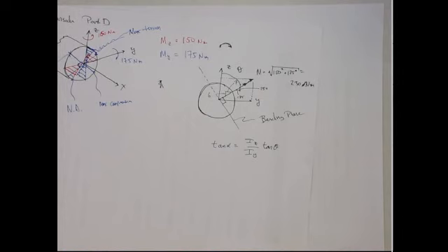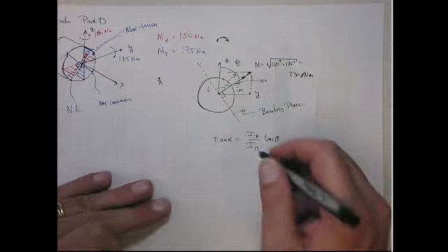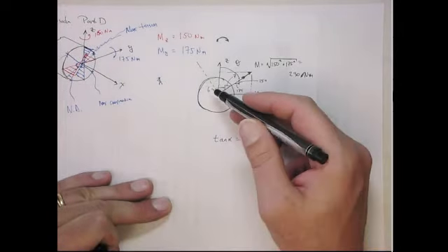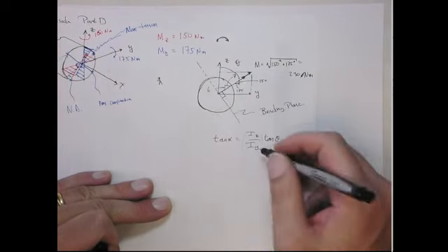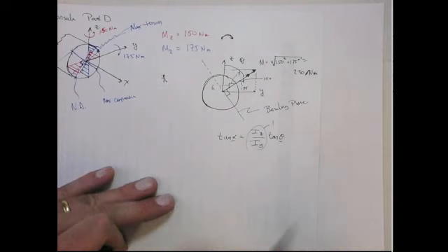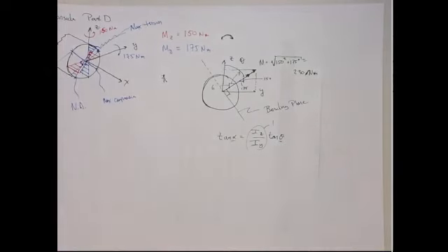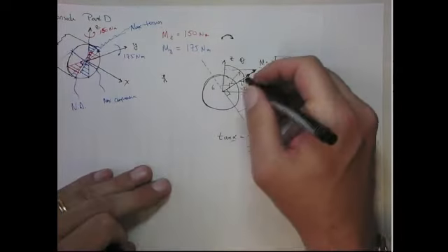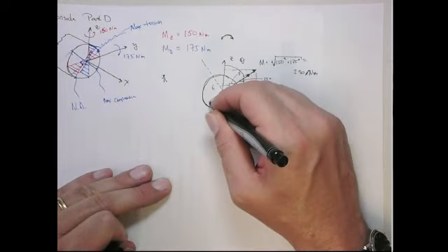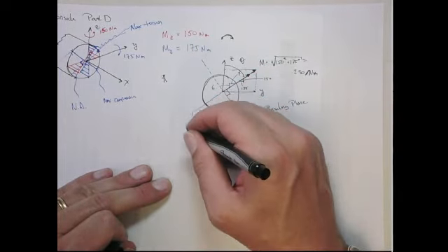It's z on y, yeah. Okay, it's z on y. So I got it right. But these I's are the same because it's a circular cross section. All right. So this is actually going to be 1. So that means the tangent of alpha is going to equal the tangent of theta. Or in other words, this plane here is going to be the neutral axis.